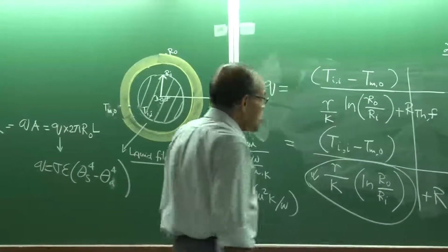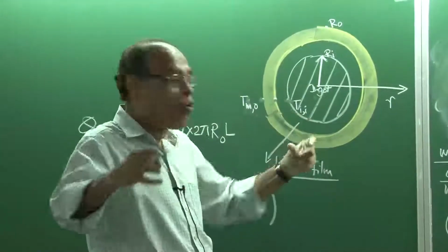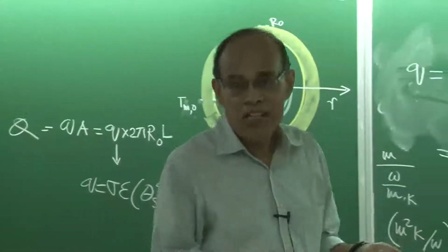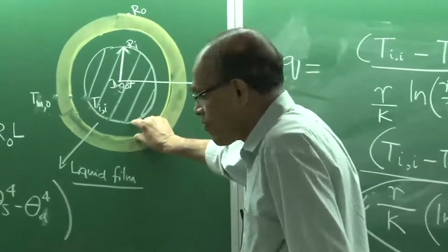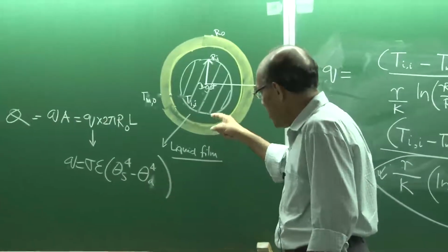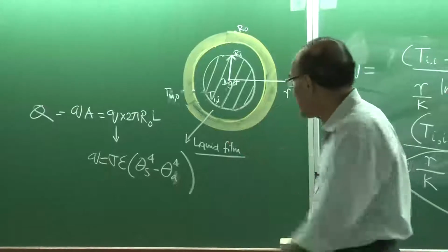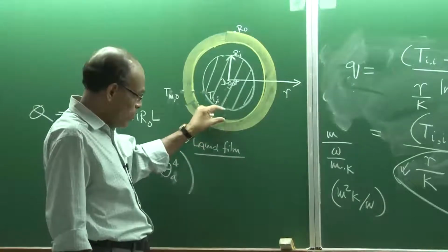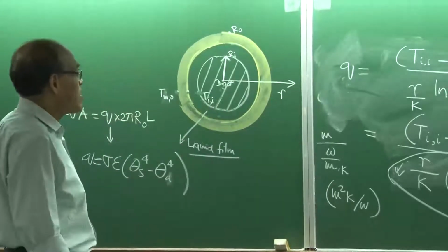Now, when the mold is being stripped, it is also possible to find out the expansion of the mold and the contraction of the ingot, exactly, by knowing the coefficient of linear expansion and contraction of the material. So this space can be calculated, and if you know the thermal conductivity of the powder or the liquid material which has melted here, you should also be able to find out the resistance offered by it.